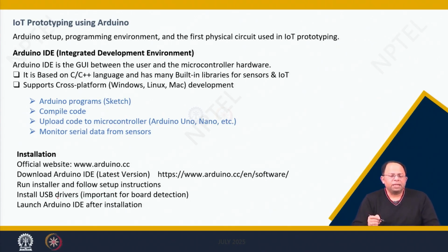So this Arduino IDE supports cross-platform development between Windows, Linux, Mac, and so on. The programs that we write are known as Arduino Sketches, and then we can compile those programs, and finally we upload the code to the microcontroller, whichever microcontroller we are using, and then finally we can also monitor what is being executed in the microcontroller via the serial monitor.